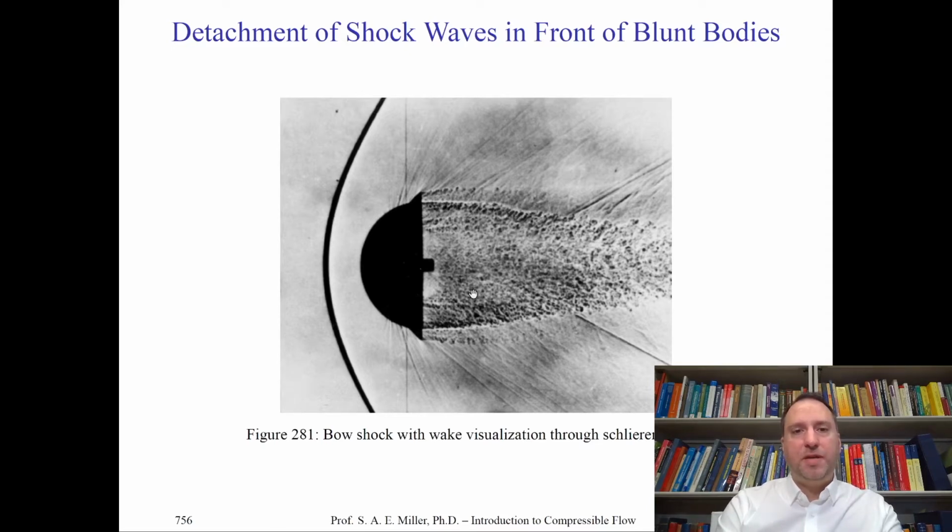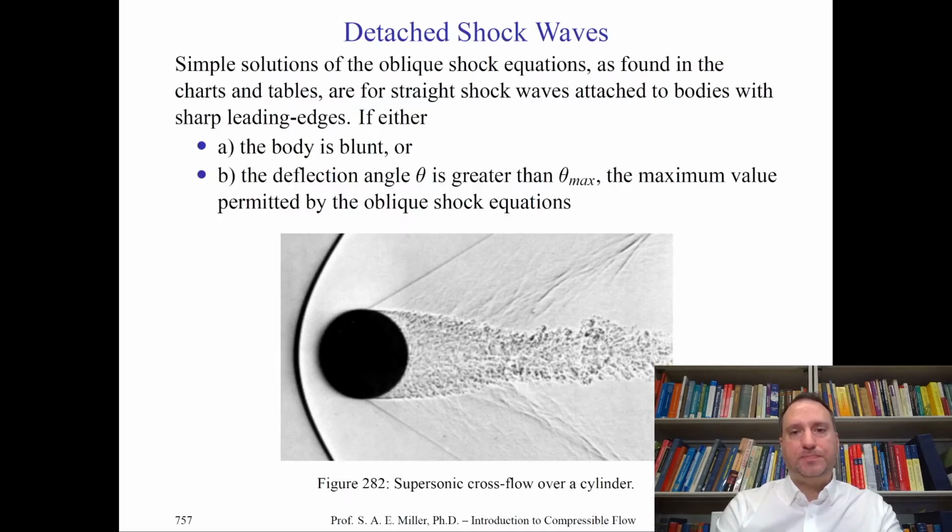We then see flow separation in a large and strong, very compressible, turbulent wake behind the vehicle, which is like this granulated material. We also see a number of shocks and expansions coming off the material because, of course, this is a supersonic type shear layer. So we have supersonic flow on this side of the flow, and in the turbulent wake, it's very likely subsonic and some recirculation happening. We'll try and look at this particular image further.